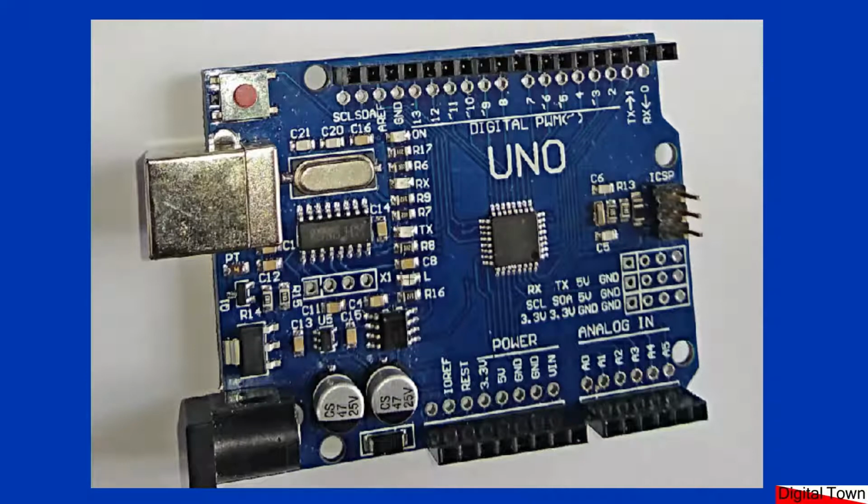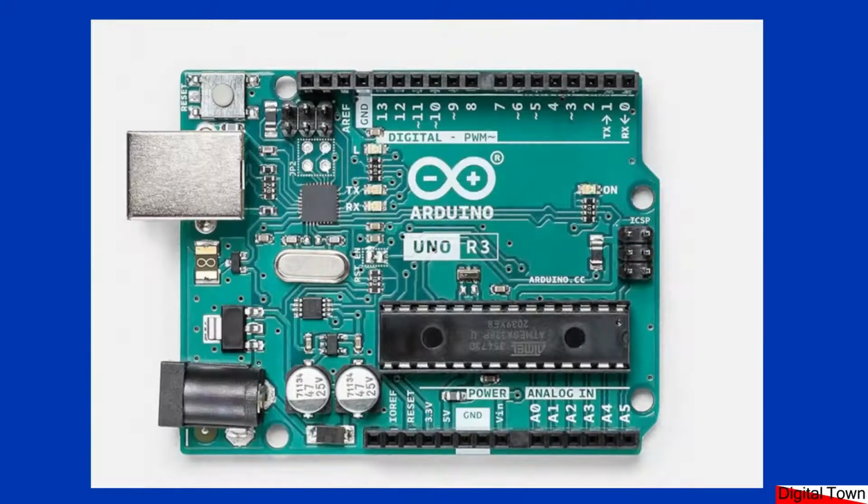Now, just while we're looking at this board, sometimes when you're uploading your code, you will see the RX LED light and the TX LED light. That is when information is being sent to the Arduino or from the Arduino via the serial port, which happens when you upload a sketch to the Arduino. And of course on this one there's another LED up here, to let you know the Arduino is attached. So the LEDs may be in a different order, they may be in different places, but they basically do the same thing. As we can see, the on LED on a genuine Arduino is down here.